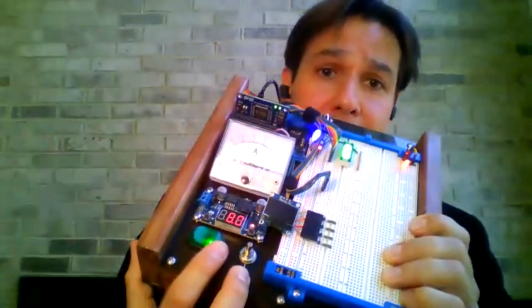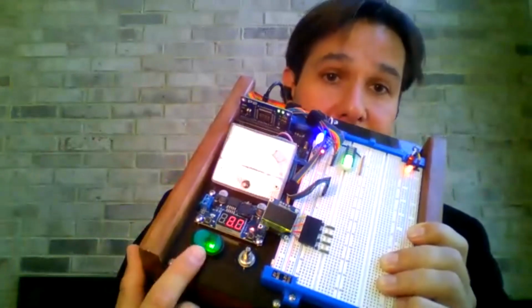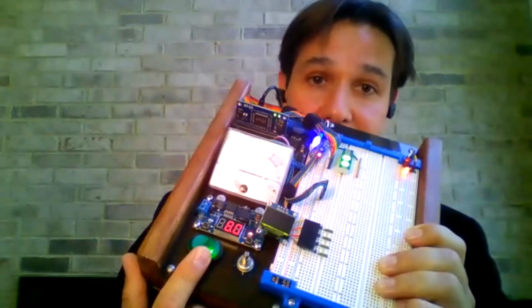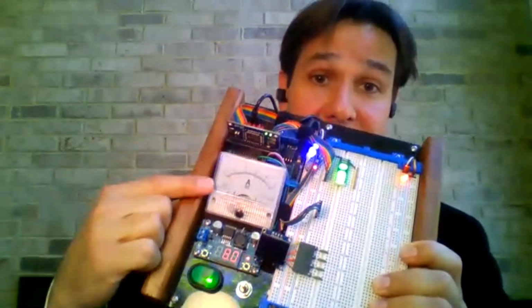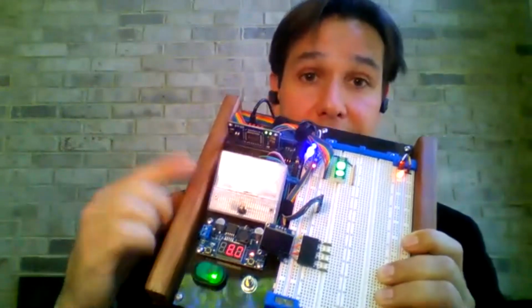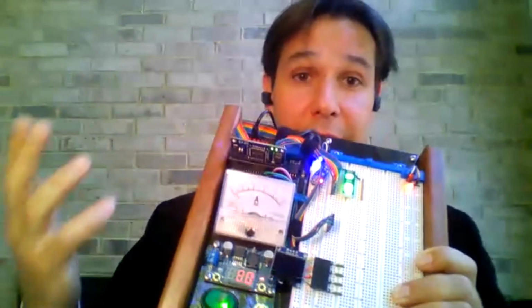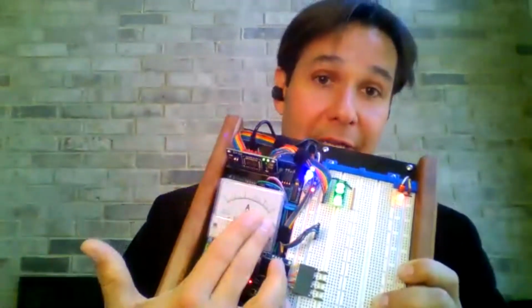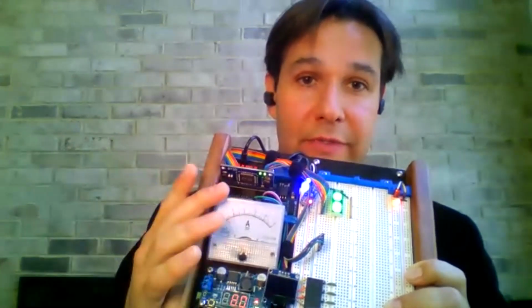Also, everything runs through this illuminated power switch, which is nice. So if things start shorting out very quickly, this dims, that's a sign to the students that something's bad. Usually the power will dip on the display here. And then we also have this nice analog amp meter. This is also really useful, particularly for teaching the mechanical engineering students, because they don't really conceptually understand current flow. When they see this thing spike, they can say, oh, I'm doing something horribly wrong. So just having that visualization, I think, is a huge safety device.